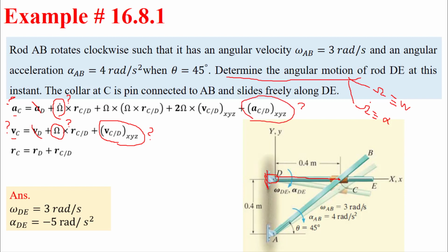So how many equations and how many unknowns? 6 unknowns. And how many equations? Actually, we have two, okay? But you know very well that every one of them is divided into two equations. So we have the I equation and the J equation. And here the same, we have the I equation and the J equation. So how many unknowns in total? We have 6 unknowns with 4 equations. So we have 2 extra unknowns, AC, BC.